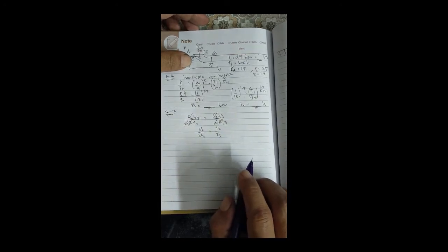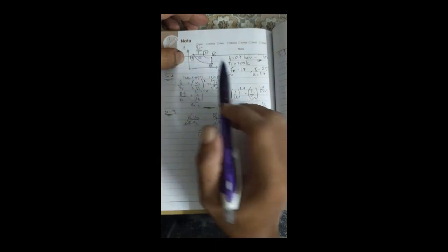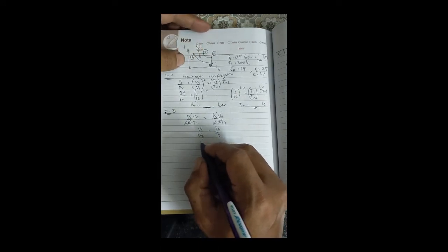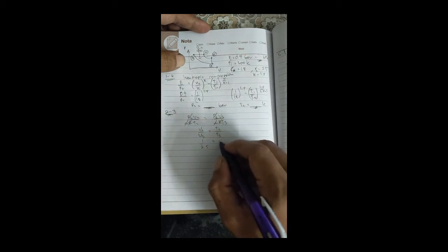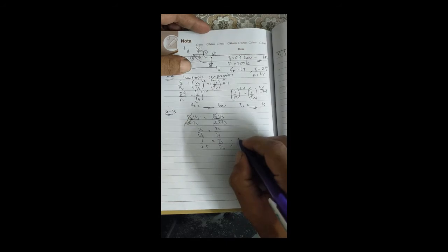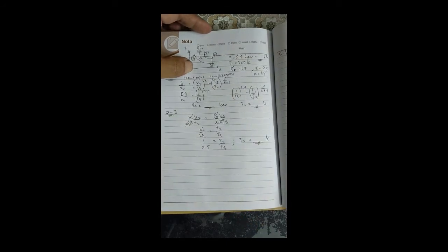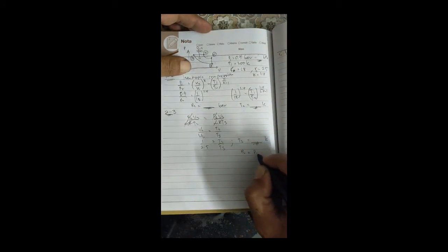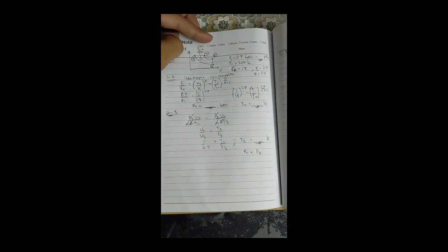So 2 to 3 is the cutoff ratio, V2 over V3 is 1 over 2.5, equal to T2 over T3. Therefore we can calculate T3 in Kelvin, and P2 is equal to P3, because it is constant pressure.